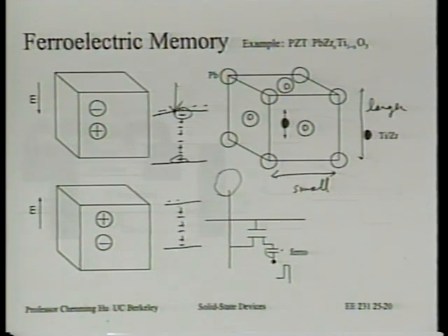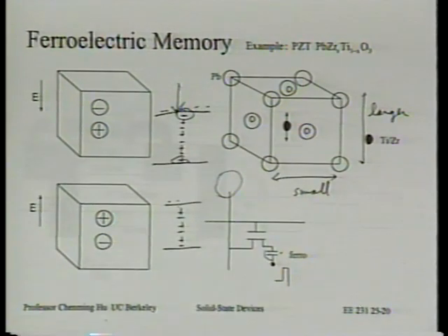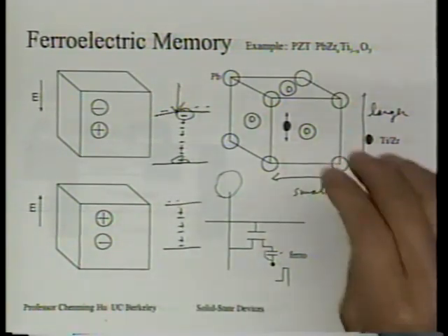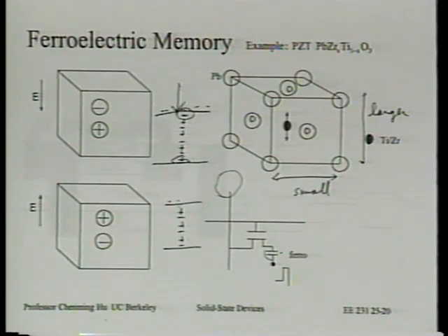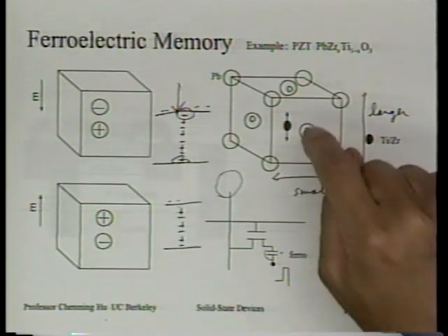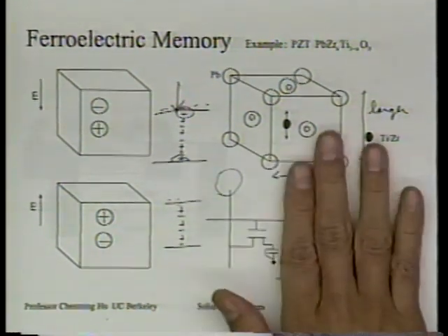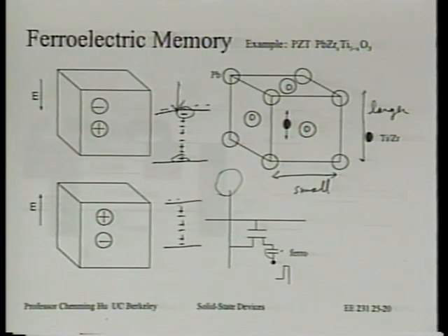And the other architecture is, for example, non-destructive reading. The easiest thing to do, you would say, why don't I simply replace the SiO2 gate dielectric in a MOS transistor with this film? In principle, you can. And with the two polarizations, your VT will be different. Turns out the problem is, if you have any SiO2 in the system, you have two dielectric films now. You have two capacitors in series. One is this capacitor, one is a thin SiO2 film. Because the dielectric constant of this film is so large, most of the voltage will be dropped in that thin SiO2 film, not on this one. So it's going to be a hard time programming and erasing.